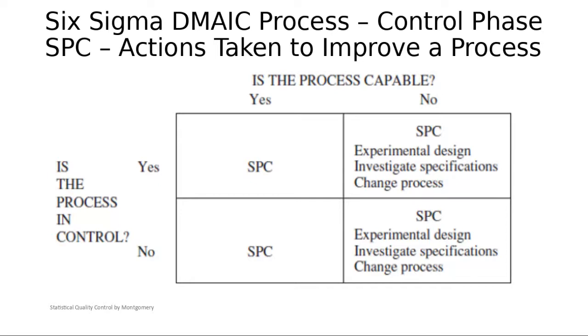Then every time you are hitting the control limits, you are hitting the specification limits, and so on. So you have to make sure that your process is capable before you implement the control charts. Your specification should carry the control limits. Otherwise, anytime you exceed the control limits, that means you are exceeding the specification limits. All of this will be further explained in the future chapters when we come to the control charts.